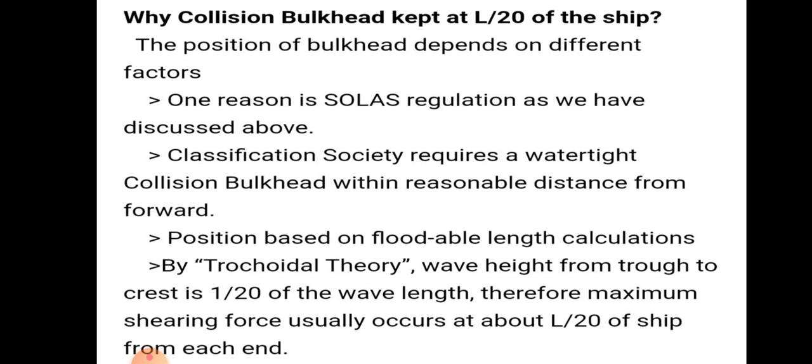Position is based on floodable length calculation. By trochoidal theory, wave height from trough to crest is 1/20 of the wavelength. Therefore, maximum shearing force usually occurs at L/20 of the ship from each end.